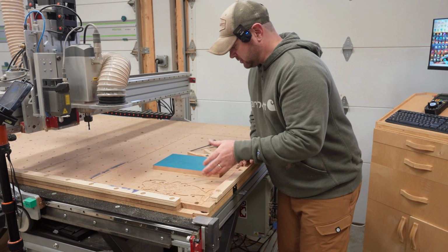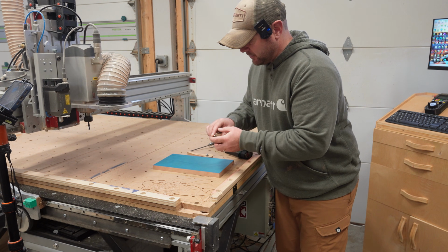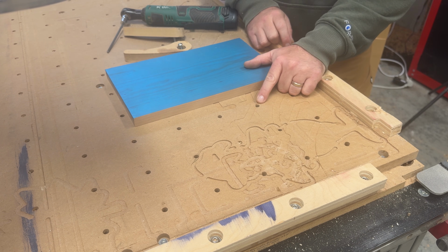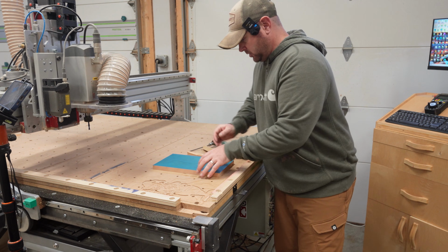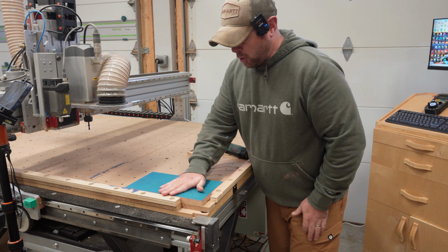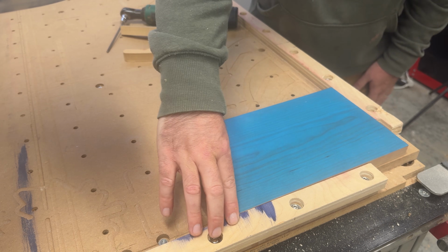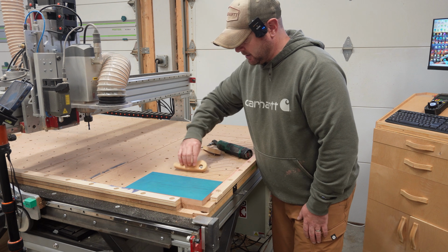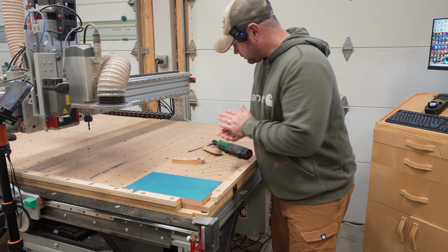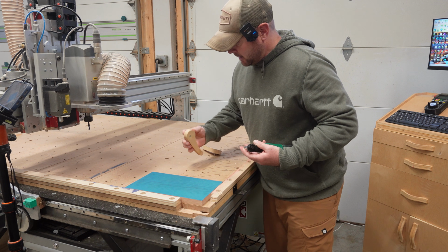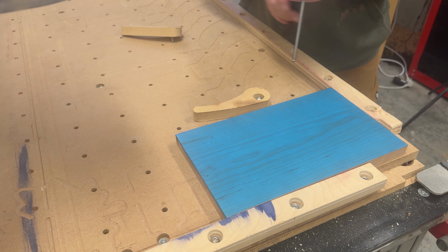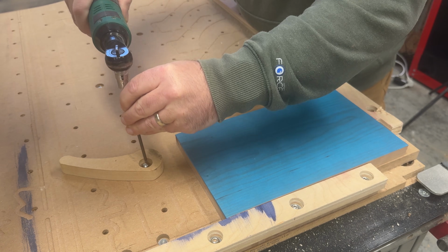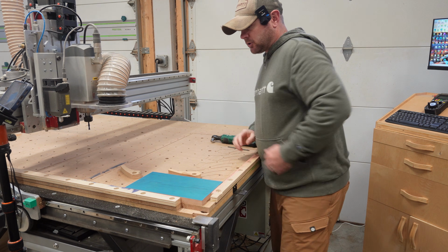So for me, I've built a custom spoil board, and it uses these quarter 20 bolts with an Allen key top to them, and quarter 20 nuts that are underneath the table that accept the bolt. So what I do is I take my piece, I secure it in the corner, and you want to make sure when you're first setting up your CNC that you have a nice square corner guide rail if you're going to do this method, because you need something to secure the piece to. So now I'm going to take my bolts, place them in, lock them down. One there, and one there. All right, those are locked down.